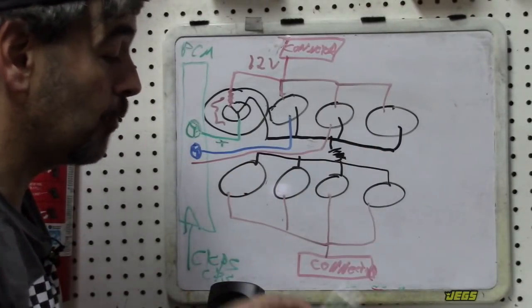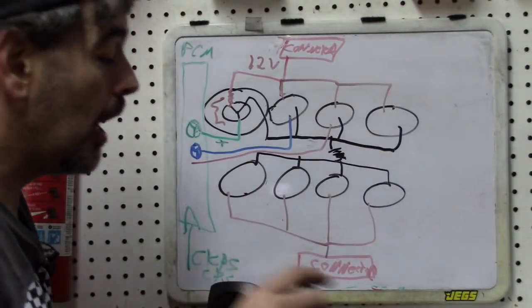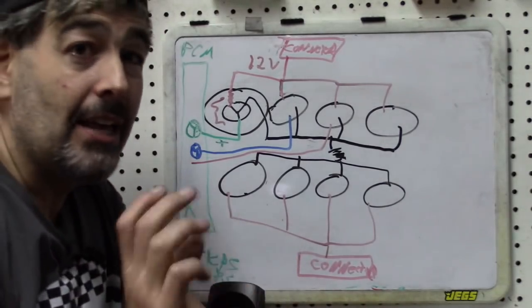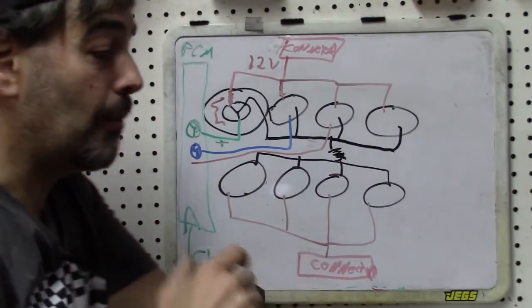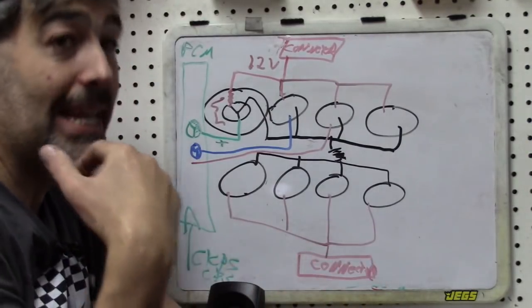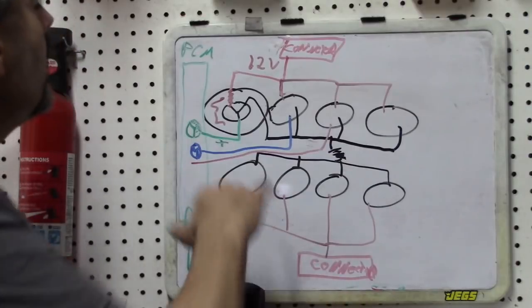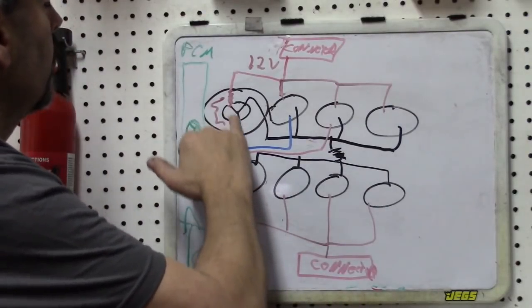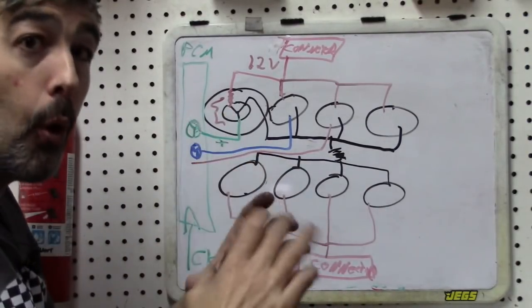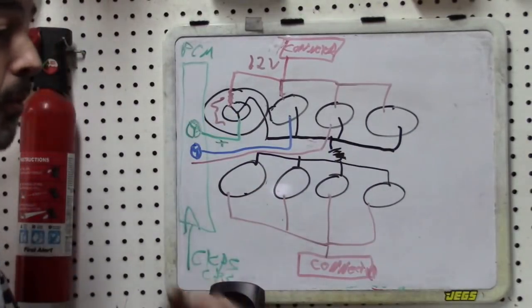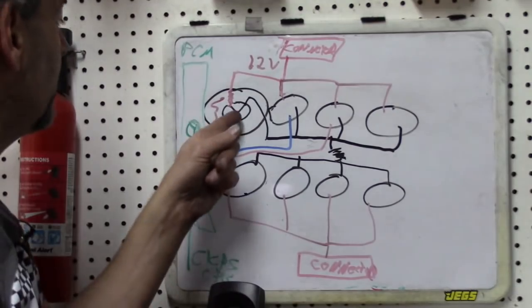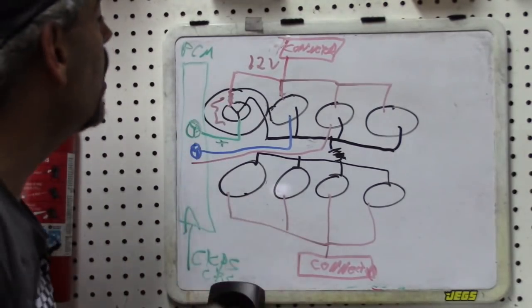And as we know, we get the spark when that electrical circuit is discontinued. So the opening of that switch, so that we stop the current flow in order to get the spark to jump, is actually going to be controlled directly in that coil by that transistor, not through the ground side switching. So when we stop the current flow, opening the switch, it's actually in that coil.